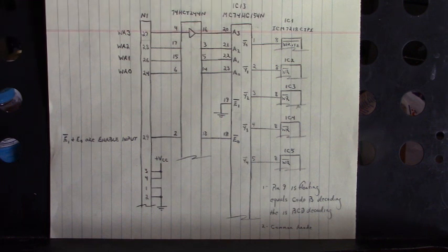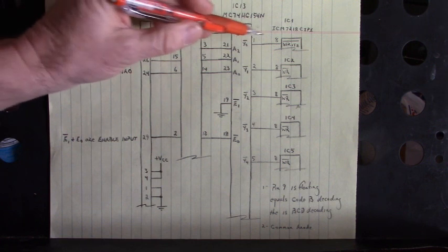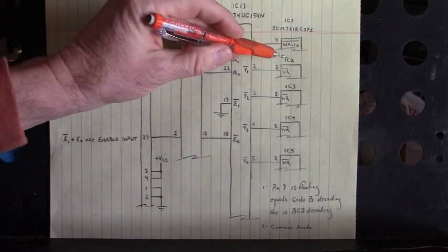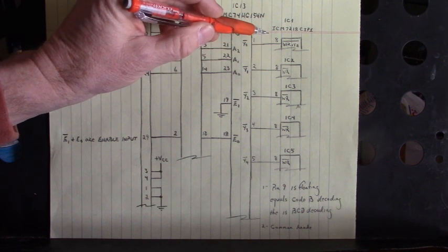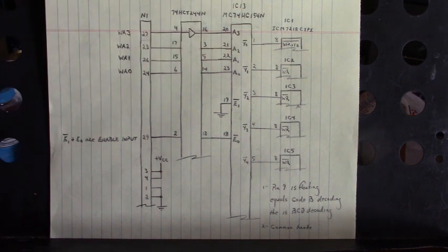When we select which digit address, which 7-segment display we want to send the data to, and we put the selection of that data, 0000 through 1111, on the input data pins, and we drive this input low, it'll be high to start out with, when we drive it from high to low, back to high, that data is applied to that 7-segment display.